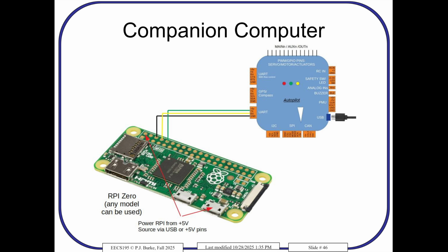There's no file system really. You can't upload any code to it. So it just does what it's told, but there's no way to do any real scripting on there. On the most recent microcontrollers, the H7s, you can upload a short Lua script, and that'll run within ArduPilot. But it's a pretty low amount of processing power.